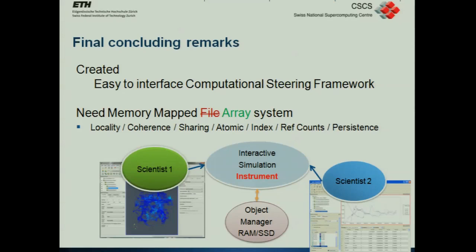And so we can effectively, over here, actually, I got a bit ahead of myself, but over here there was a wedge. What we've done is we basically said, stop the animation, reload this new mesh, and then we can connect a pipeline in ParaView. So we can say, take the mesh, that was nasty. We can say, take the output of the simulation, apply this filter to it, apply that filter to it, resample that, apply that to this.